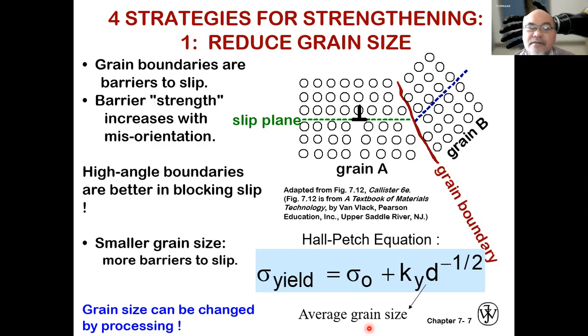Yeah, remember like this. When you have this grain A with its internal slip plane and internal edge dislocation, when you apply force, the slip may occur, and may slide and move, yeah, dislocation motion, until it reaches this edge.